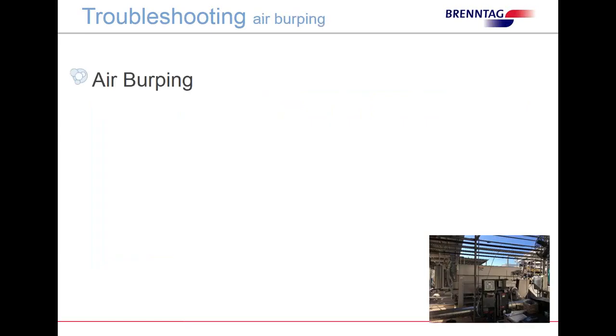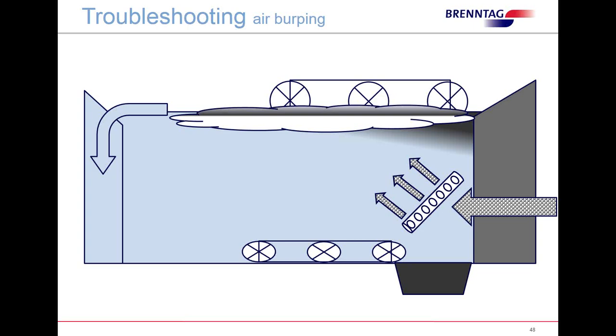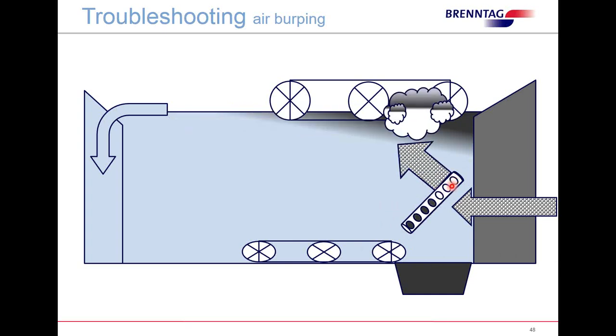I want to talk a little bit about air burping. Basically, one of the problems that causes air burping is the distribution head plugging. Now, if we go back to this depiction, you remember the header down here for even distribution. If we start seeing pluggage, it'll start channeling the water coming in, which causes large bubbles and uneven distribution on the top, causing problems on the top of the DAF unit, churning the water up, causing potential carryover out of the DAF.